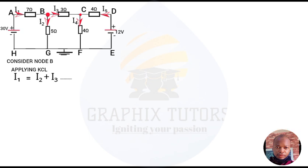I will term that equation 1. Is that okay? Now, if we move forward, we want to look for I1. To find I1, we use the voltage from where I1 is coming from. Look, I1 is coming from the 30 volts, meaning that 30 volts is the higher voltage, because current moves from a higher potential to a lower potential. So it is the voltage from where the current is coming from minus the voltage to where the current is going to.